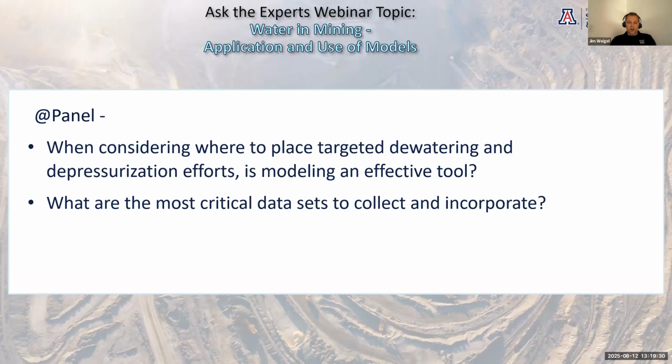So, don't be afraid, just because the model says there's something there or doesn't say there's something there, to go ahead and put in some sort of monitoring in those places where you might not feel like you have adequate characterization.